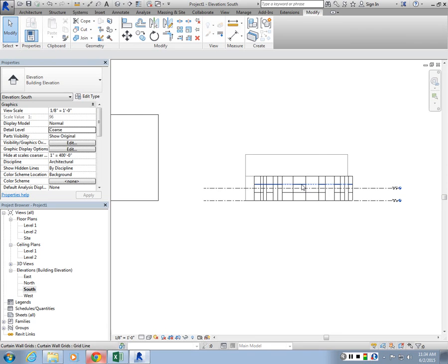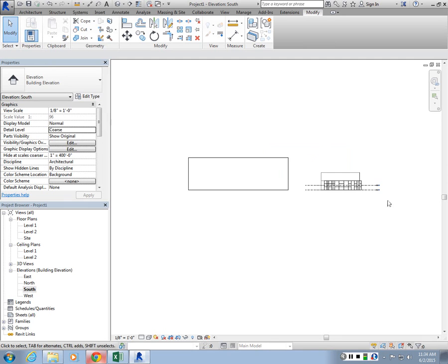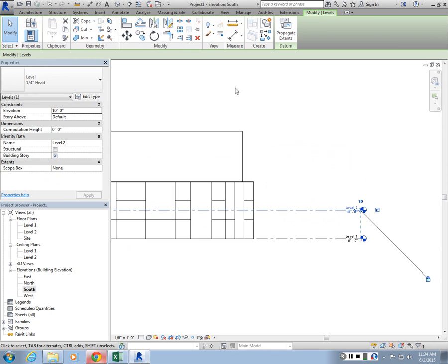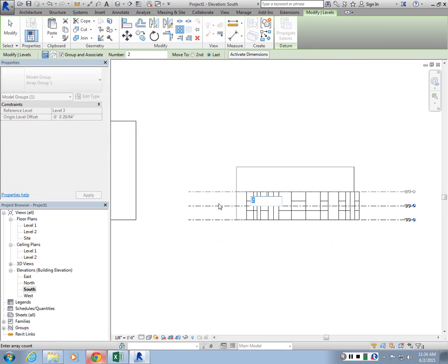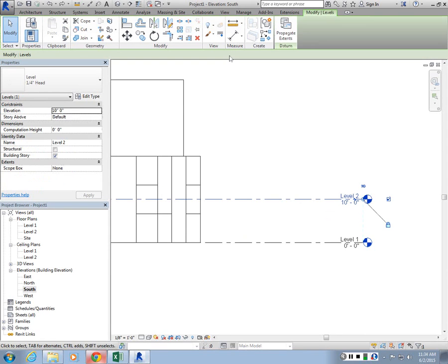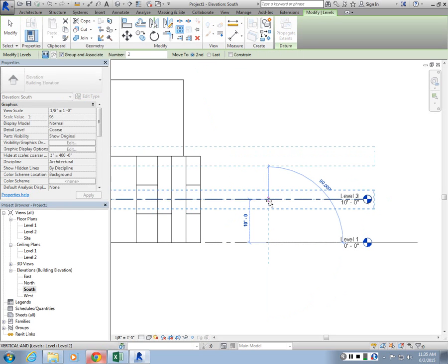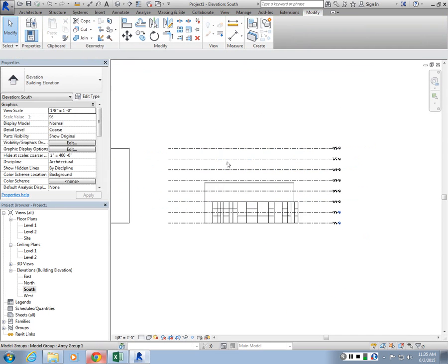So if this massing is right here, let's say I want to get the contour at specific levels, like floor levels. I'm going to create an array of floors. So I choose level 2, go to array. I'm going to copy it, and let's say we want to have 7. Let's say array again. So I created more levels.